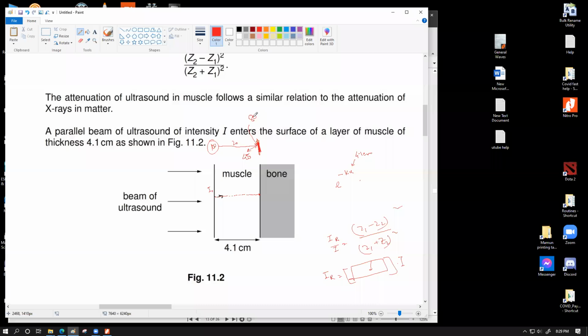This 45, as it will pass through the same amount of medium once again, will undergo a reduction of 20, which means ultimately whenever it comes back over here, it will be detected right over here by the probe. The remaining intensity available at this point would be only 25. So here we're going to have 25 remaining out of the whole ultrasound passage.